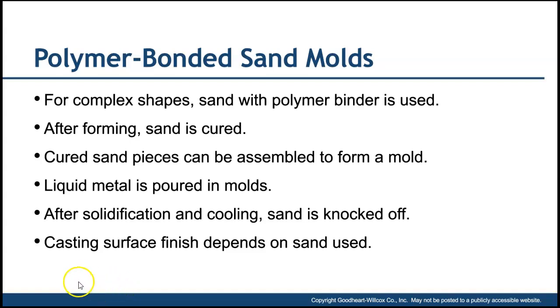Largely your casting surface depends on the quality of the sand being used too. Obviously, the grain size of the sand, a real small particle sand, is going to give you a smoother, nicer surface finish. Large size pellets of sand will be more rough.